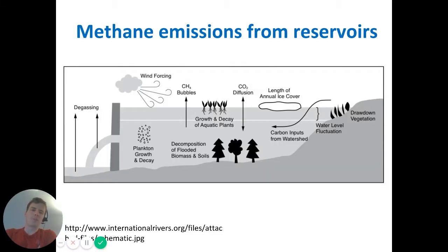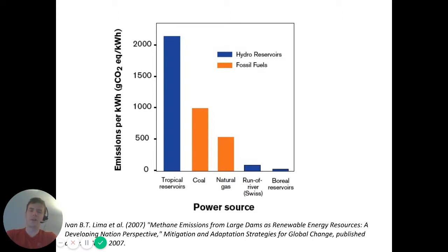Other potential environmental impacts from hydroelectric dams and reservoirs include methane emissions. So the process of building the dam, remember, means that you are flooding very large spatial areas behind the dam. And so the organic matter, the biological matter that is submerged, can decompose. And as it decomposes, it may release methane into the atmosphere. And so this is a source of great uncertainty about what methane emissions from new hydroelectric dams are. And the general research that's come out about this suggests that the siting of hydroelectric dams matters.